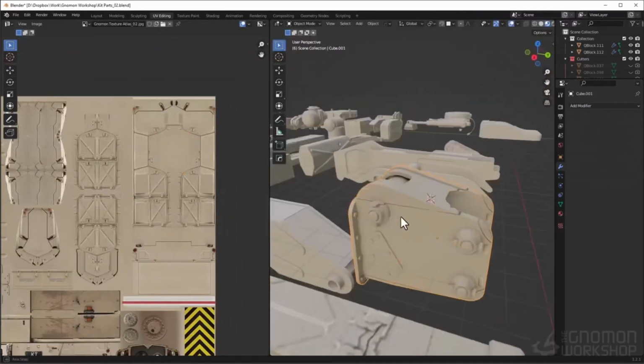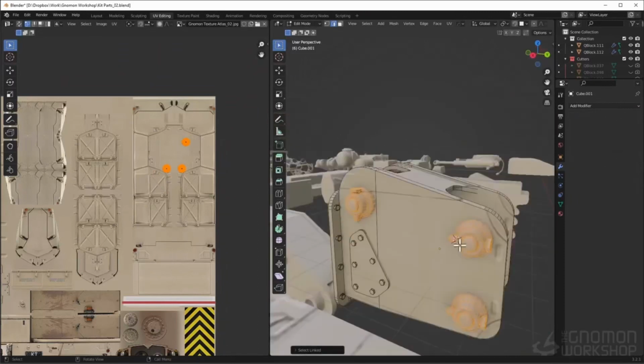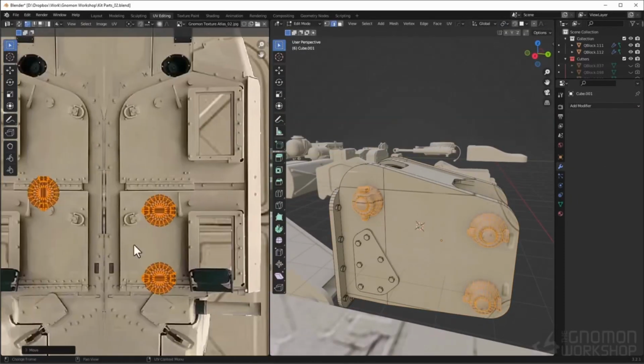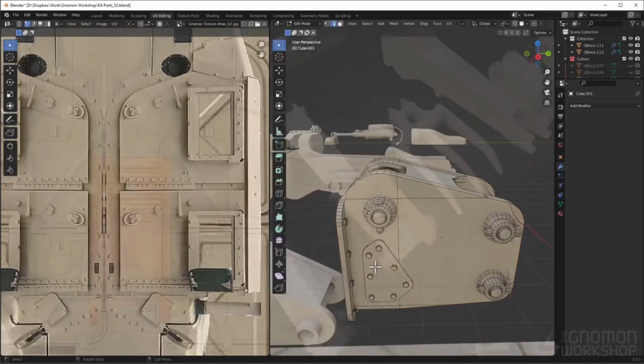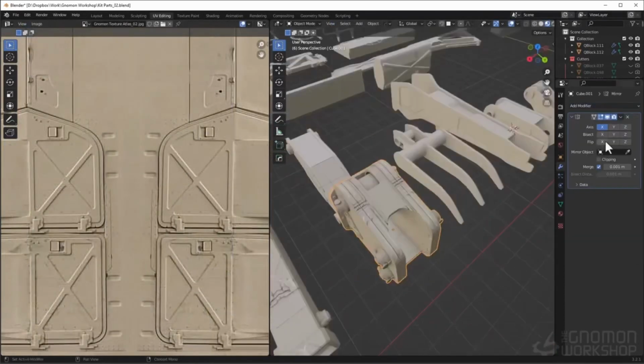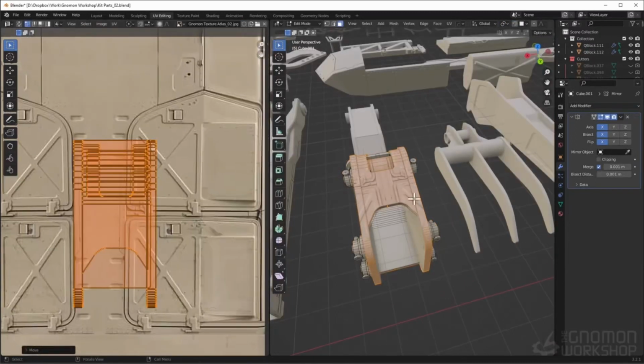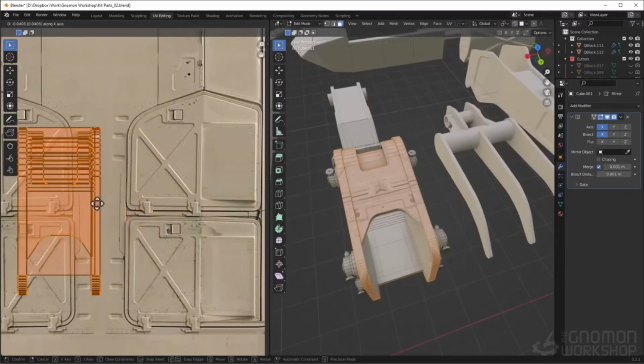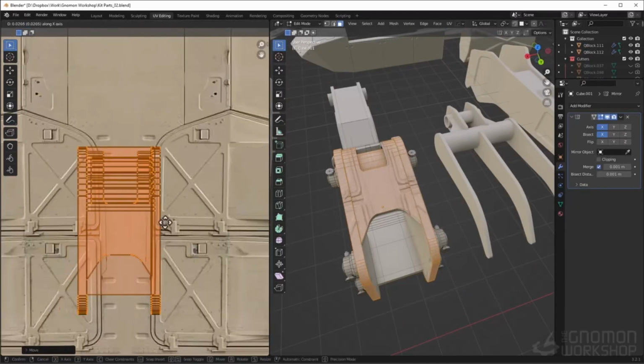Just to note, in objects that have multiple parts, I select the separate parts in the objects using L and move them around to different parts of the texture atlas to differentiate them from the texture beneath. If you add the mirror modifier to the object, provided it's symmetrical, you can then move the texture around and it will be the same on both sides. This can also create some nice unintended shapes where the texture is being mirrored along the center of the object.